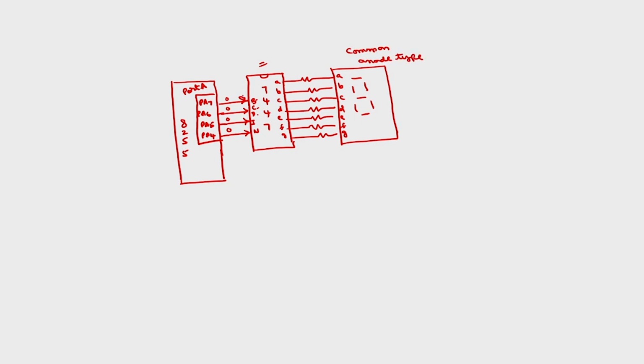If I call these inputs ABCD, this ABCD is going to be sent by the 8255. For the common anode type, as we discussed in the previous slide, to display 0, what is the code? C0H. Of course, this common point has to be connected, in that this is 11000000.